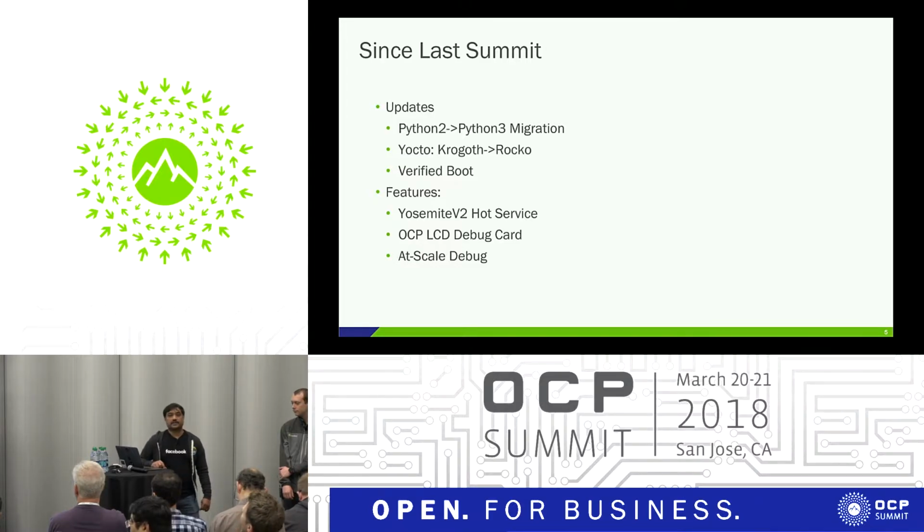And on the features front, we have the Yosemite V2 platform, which supports hot service. Previously, in Yosemite V1, we had 4 servers in a single chassis, a single sled. When we pulled it out, we had to power off all 4 of them. But thanks to the hardware team, Yosemite V2 now supports hot service, which means when you pull out the sled, it doesn't get powered off. All the systems are running, and you can replace just the component that failed and put it back. That support has to be added in the BMC, and that's one of the work we did this year. And the other 2 features, the LCD debug card and at-scale debug, I'll go into details in the next couple of slides.